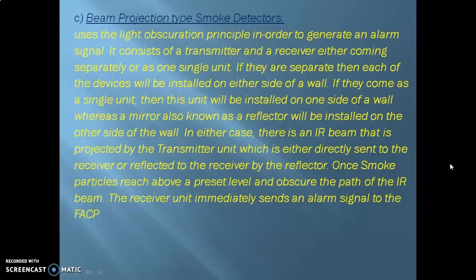And this is basically used in large areas where it's difficult to place a large number of smoke detectors, such as large rooms like auditoriums, etc., or large warehouses. So in that case, that is when these beam projection type smoke detectors are very handy. You can cover a distance of up to around 100 meters or more, depending upon the manufacturer and the extension kits that are available for these beam detectors.